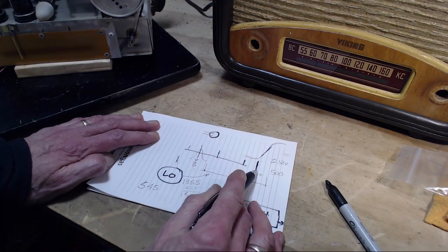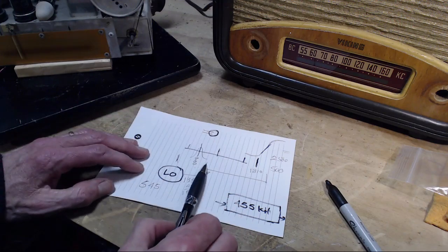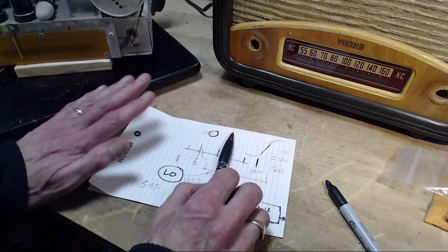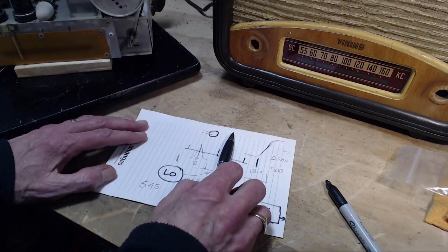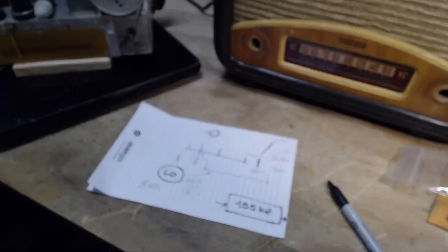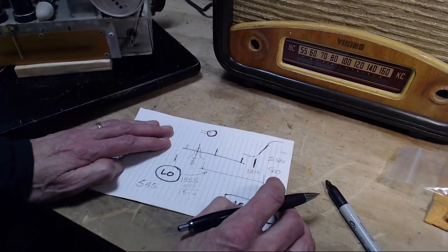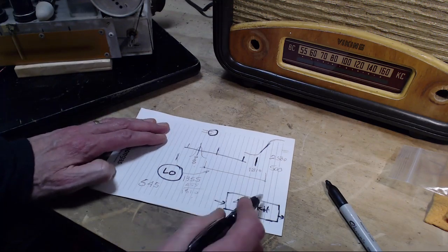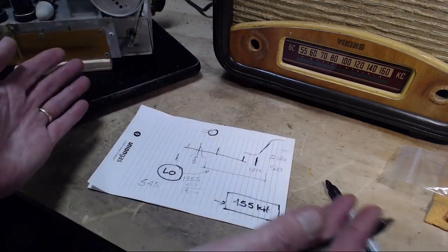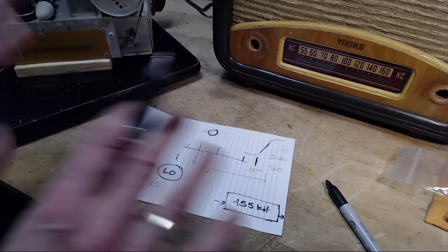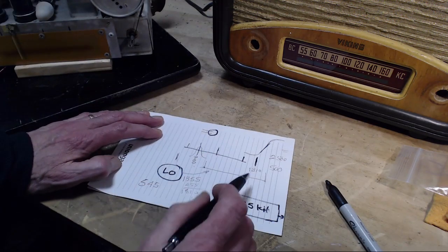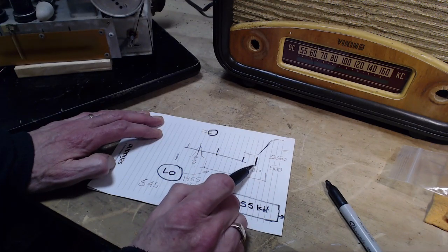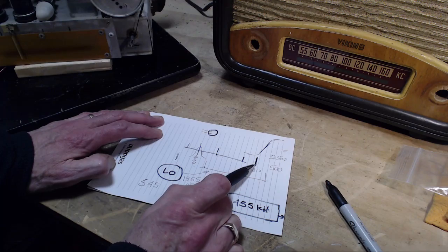And the reason they call this the image is because you can think of the local oscillator as if it's a mirror and you have an image. But that's really a bad way of looking at this. The better way to look at it is the way I'm looking at it. You're hunting for this difference in frequency, thinking about it that way, not thinking about some kind of mirror reflection image. There isn't any. So why don't we hear these? Well, do we not hear these?